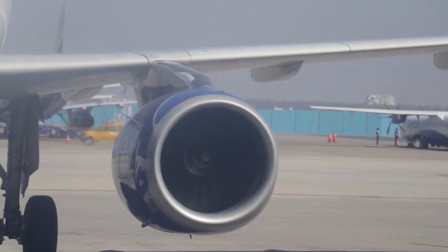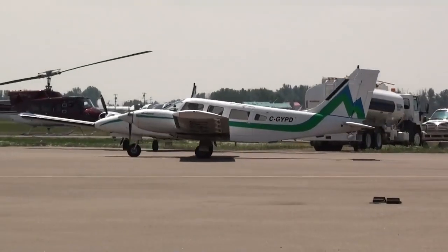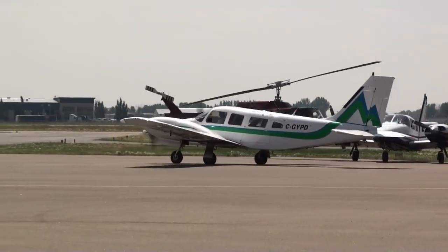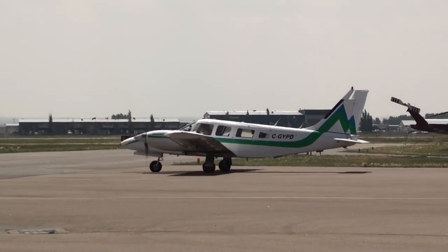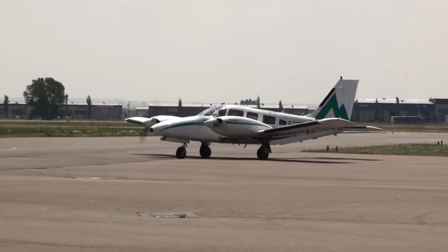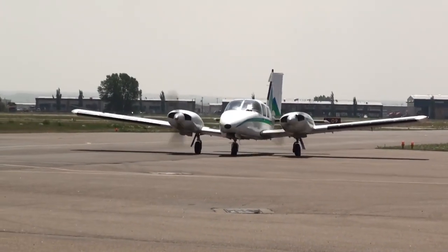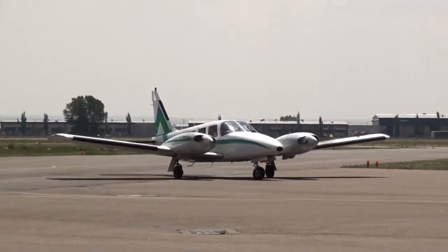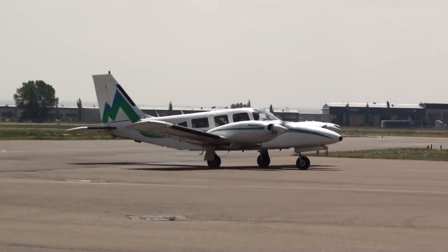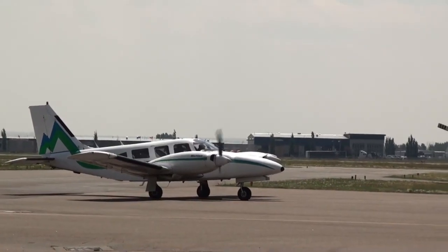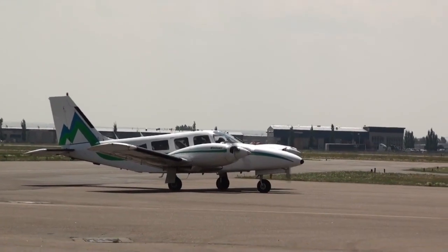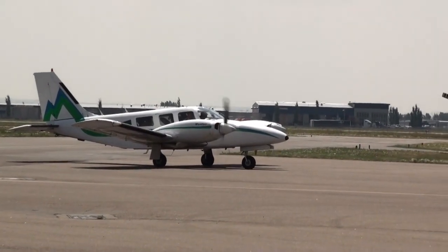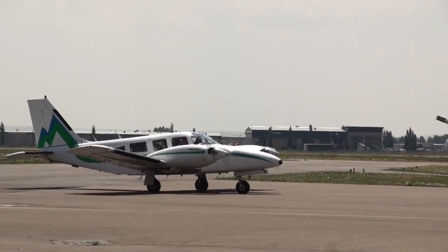We can't modify the density of the air. It's not a controllable variable. We can modify the horizontal projected area of the airfoil in order to obtain lift. But as we increase the area of the airfoil, we also increase its weight. So we have to find an equilibrium between the projected area of the airfoil, which will generate more lift, and its size, because we will also increase the weight of our airfoil and thus our wing.